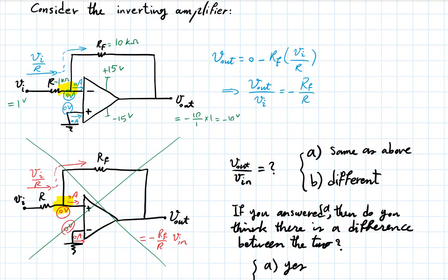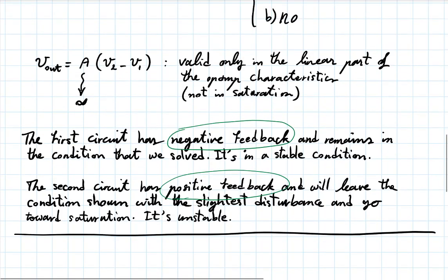Here, the way I approached it was this. I was saying, well, if I have built this circuit such that it does stay in the linear region, and I know that equation holds, and V out is a finite value and it's not saturated, then I would naturally conclude that the two inputs have to have no difference in voltage, right, from that equation. This is an assumption, if I assume V out to be a finite value and not saturated. That is dictated by the op-amp.